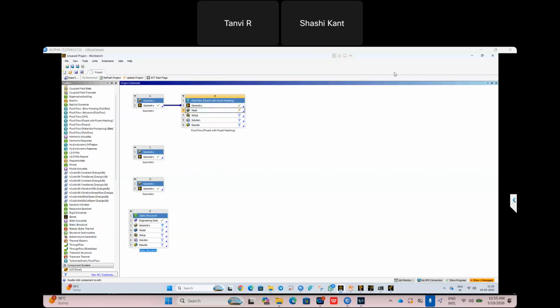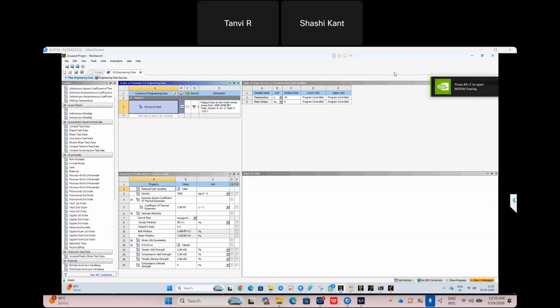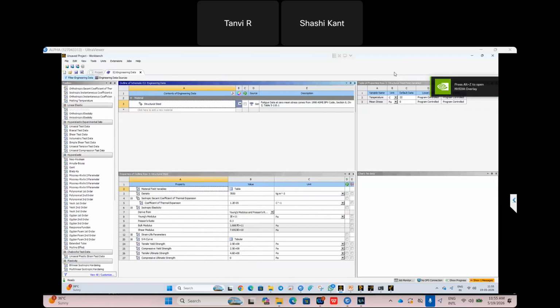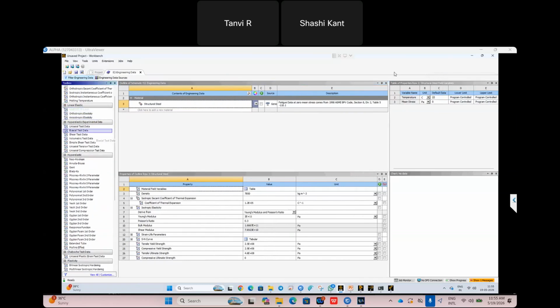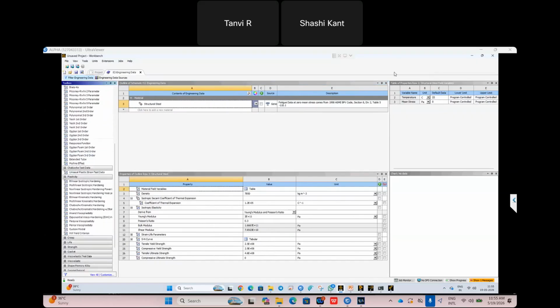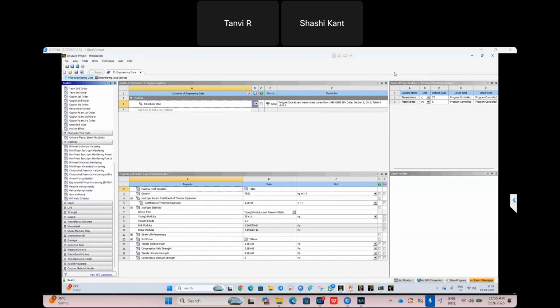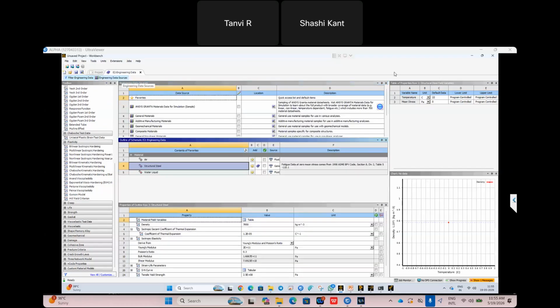And the beauty of this interface is that here you can do multiple simulations in a single physics, single window, or you can also couple multiple physics here. Okay, so in terms of structure, when you open Engineering Data, you will have a complete material library with properties. You will have elastic properties, hyperelastic properties, plasticity, and creep properties. Normally Ansys uses a standard material, structural steel, but let's suppose you want to utilize a library. So we have a library here also.